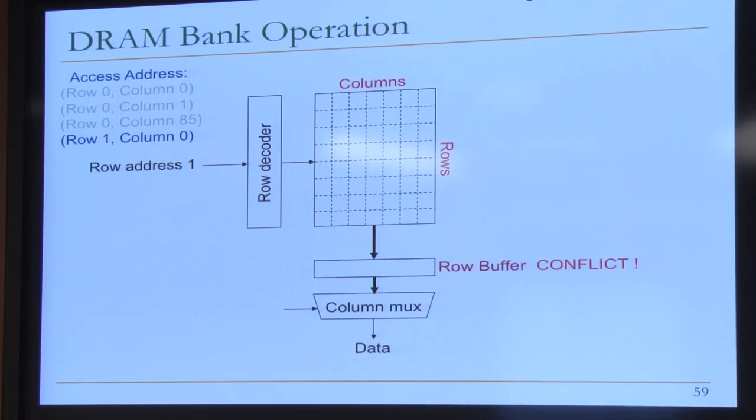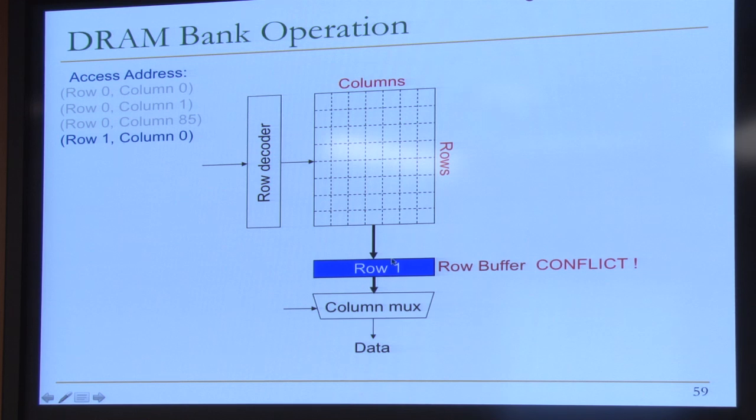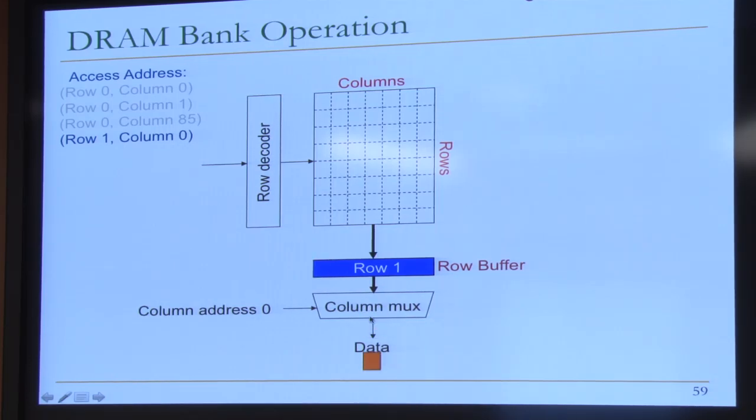And after that, once the pre-charge is done, there's a latency associated with the pre-charge command. After that many cycles, the memory controller can activate row 1, which brings the data into the sense amplifiers. And then the memory controller can send the read command to the bank to get the data. Make sense? So actually pretty simple.